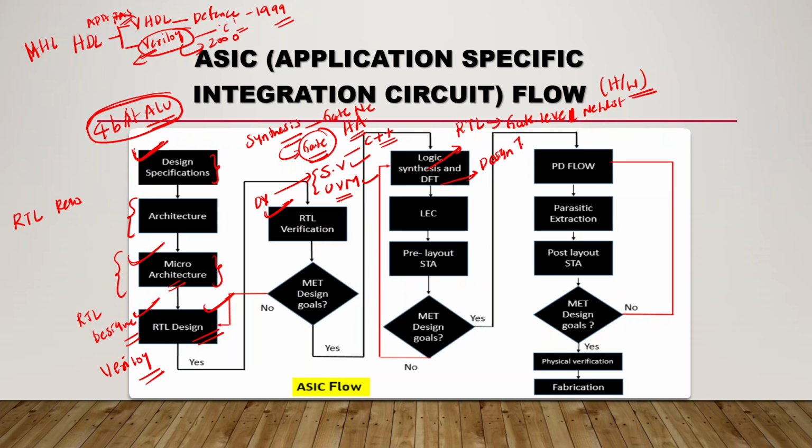DFT is design for test. For this synthesized gate level netlist, you will use some test vectors, and you need to use scan techniques and BIST techniques to check the correctness of the circuit. If you give the test vector 0 0 0, you need to get the expected output. That is DFT, design for testability.